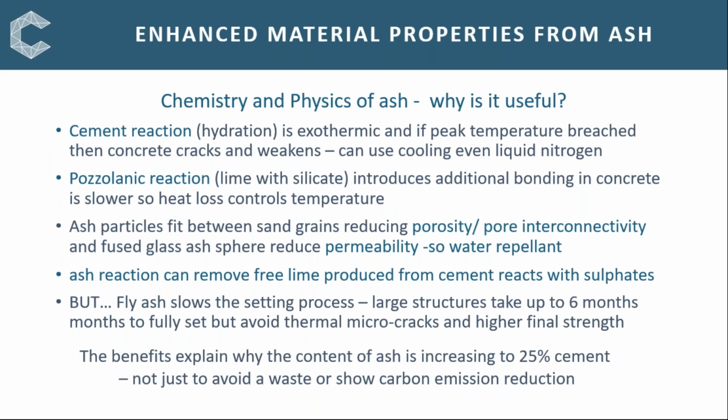So why is ash useful in construction? We've already seen the effect of volcanic ash in the durability of an ancient structure. The improved strength partially comes from the way heat is released. In the hydration of Portland cement, the temperature can rise too quickly, and if a maximum is breached, then microcracks form, weakening the structure.